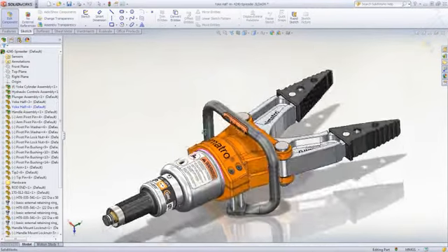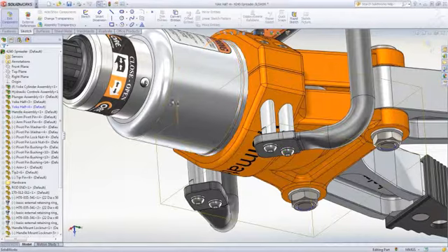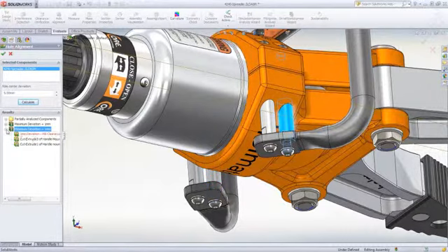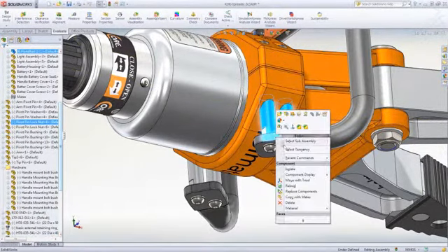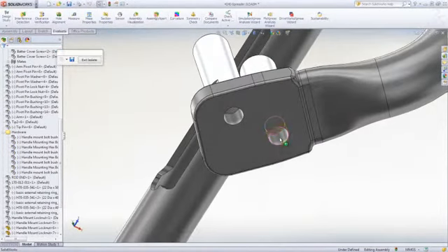To resolve the issue with the screws, the hole alignment tool can be used. This tool checks the assembly for any holes that aren't lined up. The misaligned holes are listed with the maximum deviation between centers, and they are highlighted on the screen for easy identification. Using the isolate command to focus on the misaligned parts, we can see that indeed we have a problem, but it is easily repaired by changing the hole pattern.